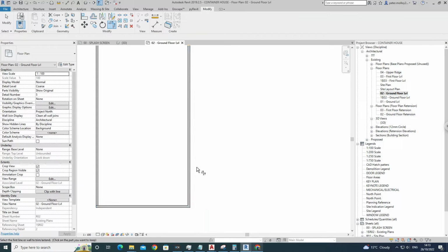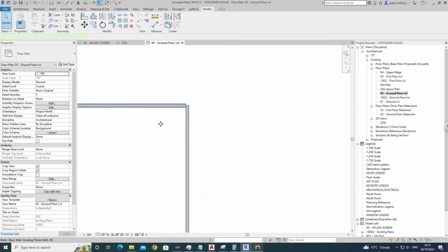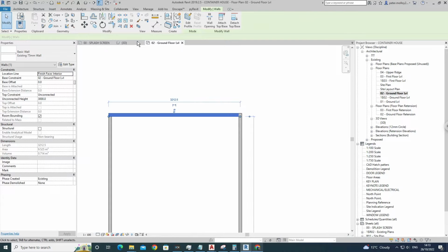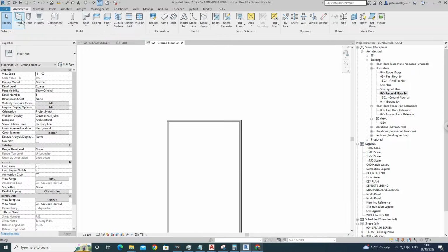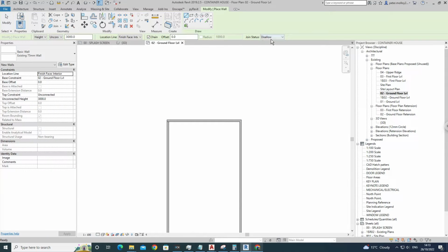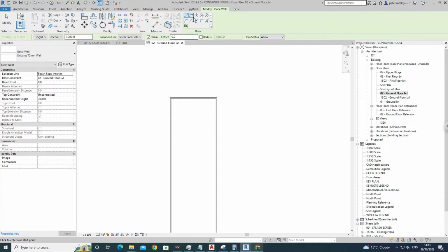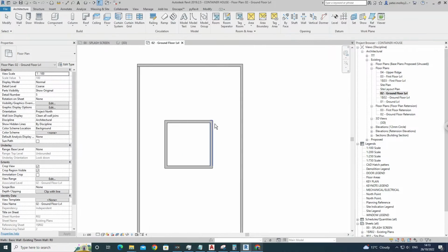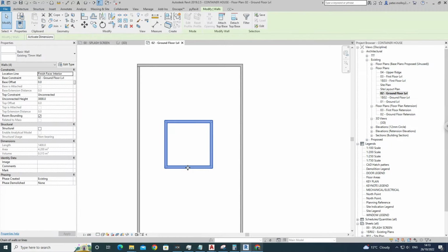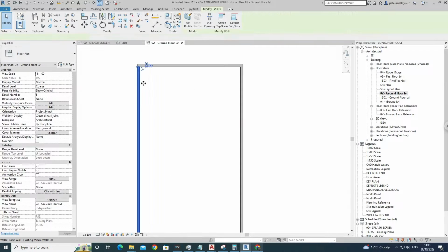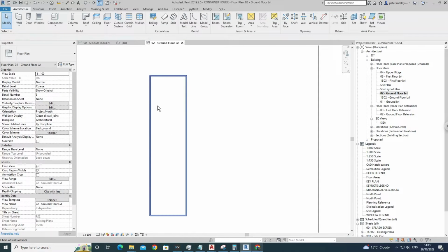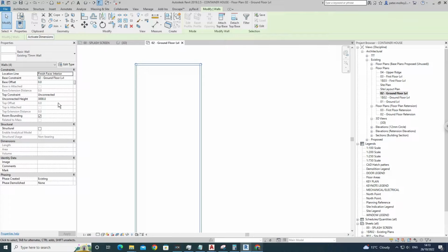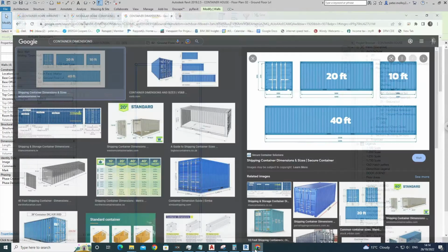It won't connect to any wall actually that it's leading to. So I just had that tab on from a previous work set. So if I come into walls here, see the way I had this join status to disallow, you want to have that enabled, just so all your ones join together cleanly. So now once I press tab, this fella's playing up on me as well. No, perfect. Just tab them all, and then I'll bring these up to, what did we say we were going to bring it up to?